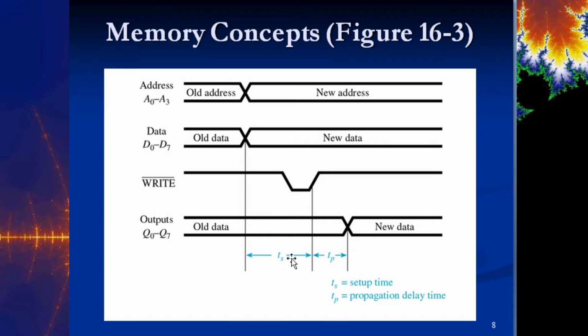So we have to honor the setup time here. And as long as that's honored, then before the outputs can change, and this is just a feature of the flip-flop where Q follows D, it's not an instantaneous change that happens, right? There's a propagation delay after the data is passed through and locked into the output. And so there's a little bit of time here.